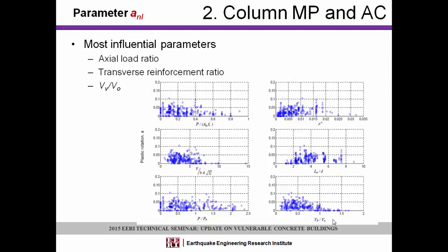Anything above 1 should signify a shear failure, and currently what ASCE 41 does is at 1.01, this is a shear failure. This is categorized as a condition 3, I believe, and your A parameter goes to 0 immediately. But what we've seen is that the V naught term, that shear strength equation, has its own scatter.